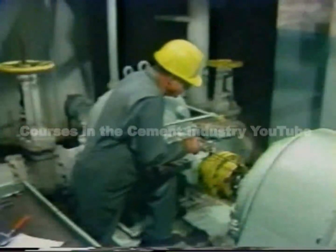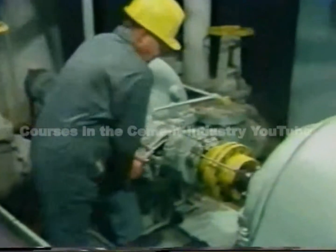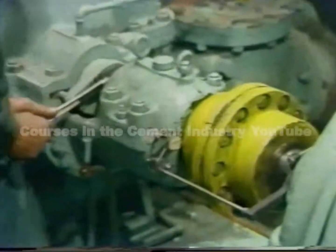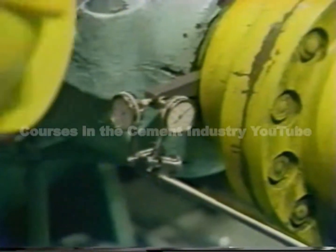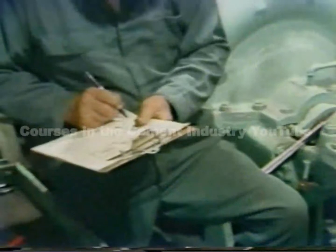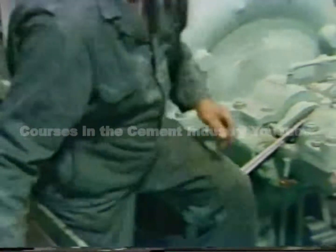The technician is about to gather his first set of readings. The first set is very important, so the technician double checks to make sure that both dial indicators are zeroed at the top. Then he carefully rotates the shaft so that the indicator post lines up with the first data collection mark. At this point, he'll record both dial indicator readings on his data sheet. He'll record on the outside of a circle the parallel dial reading, and on the inside of a circle the angular dial reading.